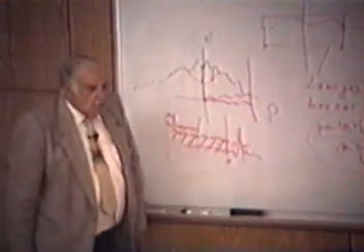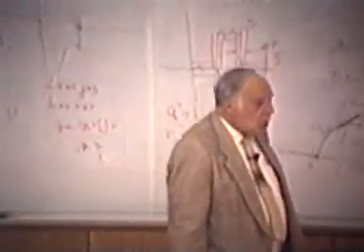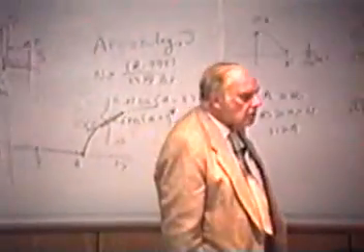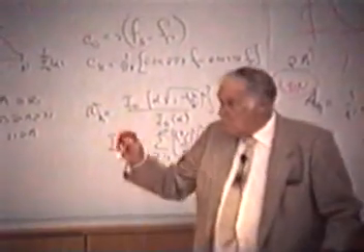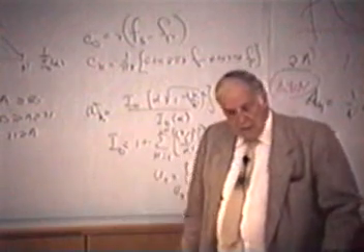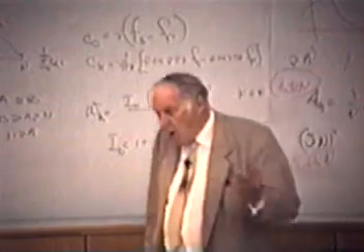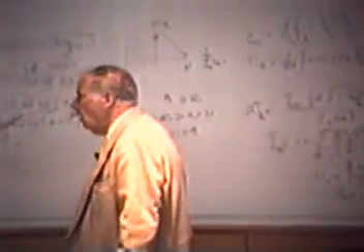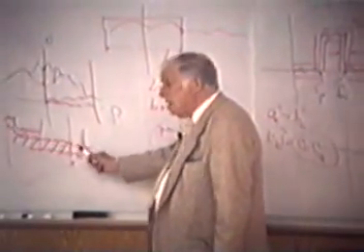So one often oversamples, knowingly, well above what you need, to try and remove the errors of the measurements of the instrument. And then you filter, remove the noises above that point, and you then have the signal freed of much of the noise. But there is no linear method which will separate the noise and the signal in the same band.